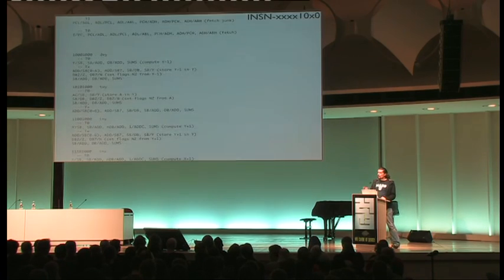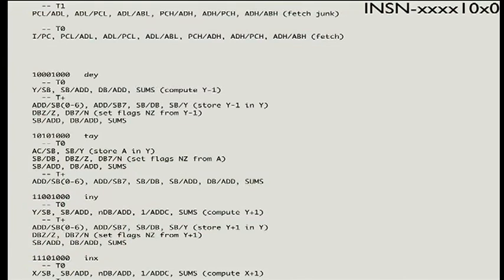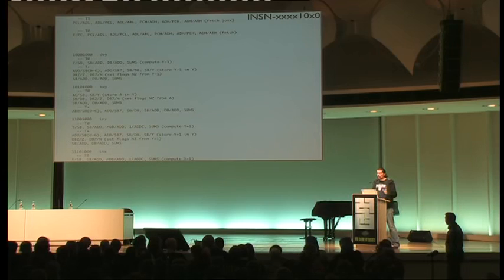So one thing that we have, some really interesting internal representation, is this mapping from the opcode to what comes out of the random control logic as the very last step. So you can rather easily look up what's going on the bus in every cycle of certain instructions. But we're not only investigating the 6502 by itself, but also the different 6502s that are out there. There are so many things to do.